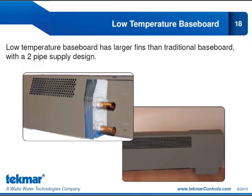The fact that we're able to include baseboard to operate at supply temperatures as low as 110 means that we can actually include this type of heat terminal in our geothermal application and still offer those very low entering load water temperatures to get that maximum heat pump efficiency.